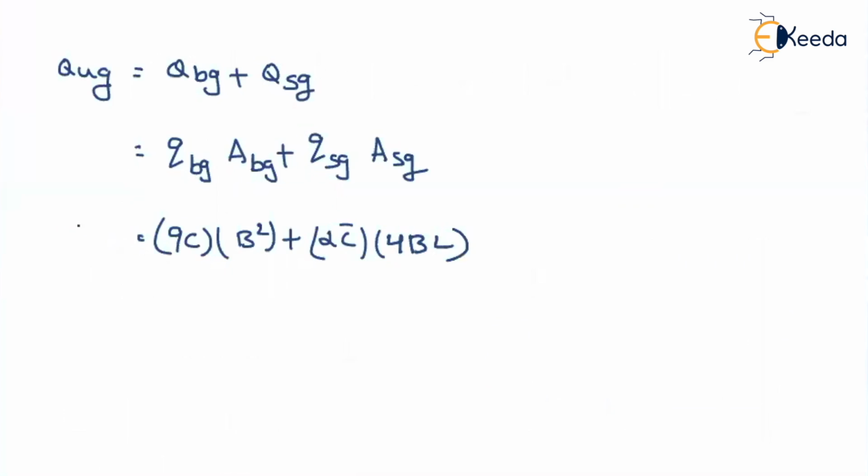So by using this relation, we will find out the capacity if there is a failure in the group action. That means we can also consider it as a block shear failure. If there is a block failure, this is the capacity. What about a single pile? That means N into Q_UP.